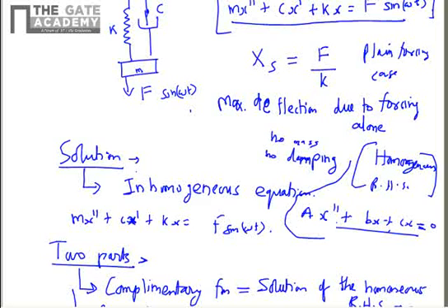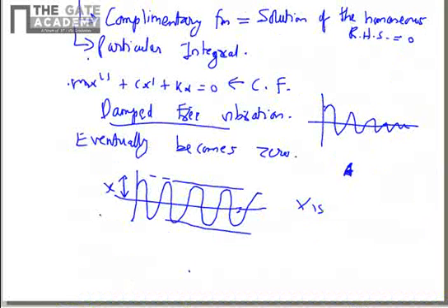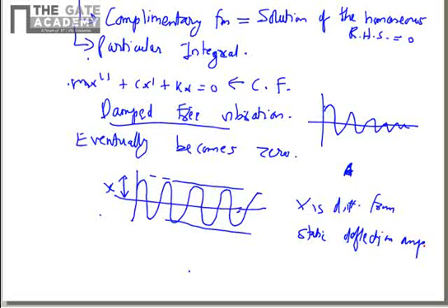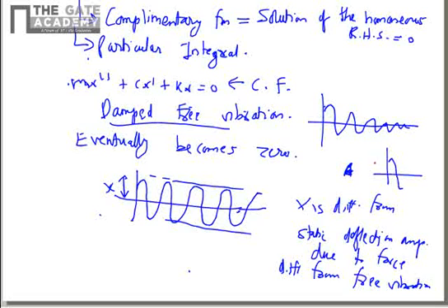In that case there is no mass and no damping, but you have a deflection also. So this x is different from the static deflection amplitude due to the force alone. It is also different from the free vibration amplitude. If you see the free vibration case with no initial velocity, the amplitude is basically equal to the initial displacement x0. So the free vibration equation is x equal to x0 cos omega t, and only the initial displacement matters. So it is different from either xs or x0 in the case of free vibration.